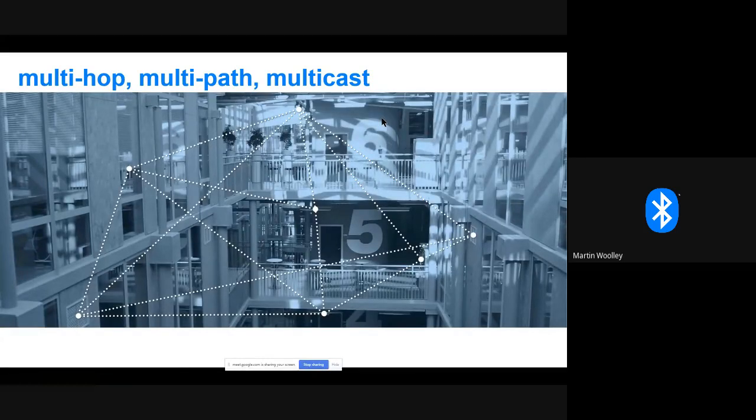But with a large mesh network, I'm very much going to be thinking about which of the devices in my network need to have the relay capability enabled and where I'm going to place them. And with a bit of thought and some testing, I'll make sure that messages can hop all the way across my network to wherever they need to be. Now, from an efficiency point of view, I can send messages from a device and I can limit how far they go. I can say, don't go more than 2 hops, because if my device that's sending messages is a light switch, for example, and I know that all of the lights on this floor of the building are within 2 hops of my light switch, then there's no reason for me to want that message to travel any further. There's no point using the radio resource on the top floor of the building when none of the lights that I want to control from that switch are there. So I have some control over how much hopping takes place, but the potential is for messages to go a really long way, and so we can have very large mesh networks.